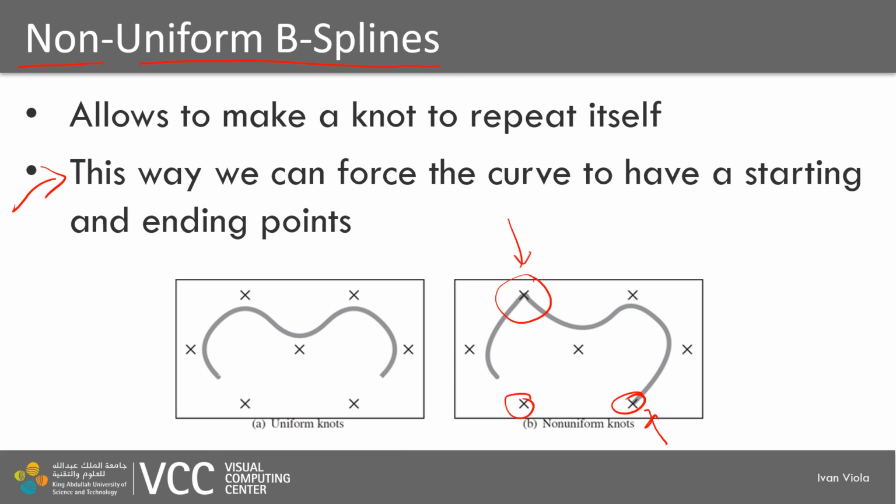The points along the sequence will usually be interpolated with some ugly shape, which is typically not so desired. So we can have an arbitrary amount of knots in this non-uniform B-spline case, and therefore we can repeat a point by having an additional knot associated with that particular point.